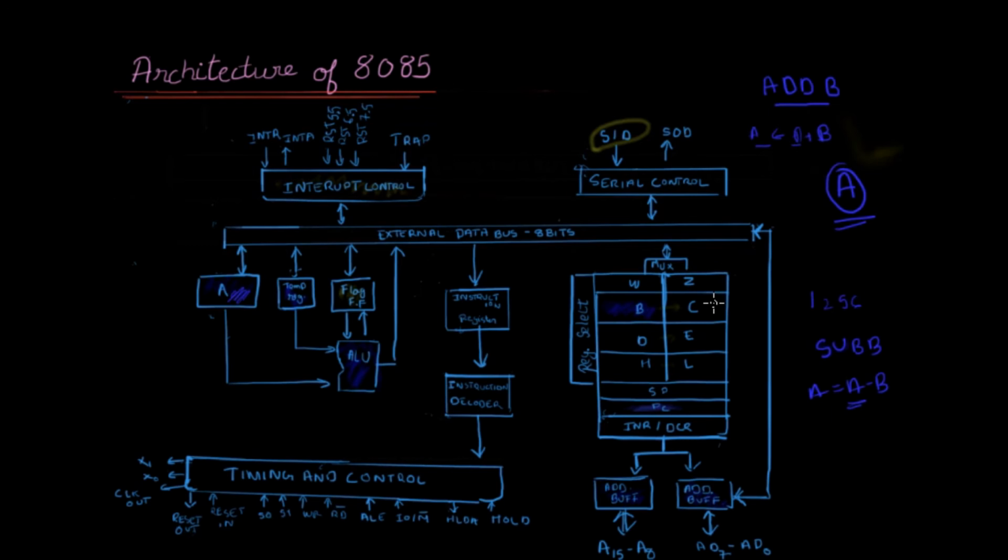I told you the program counter holds the first instruction, and this entire process takes it from the memory, through the external data bus, comes in, decodes, and then carries out the particular program over here. While that is being done, the program counter increments. It moves to the next address location, moves into the memory, takes that data and moves on. That means the instruction to be carried out comes in continuously. That is what is happening here using your increment and decrement. Now, why doesn't the program counter always just increment? What is the utilization of a decrement operation?